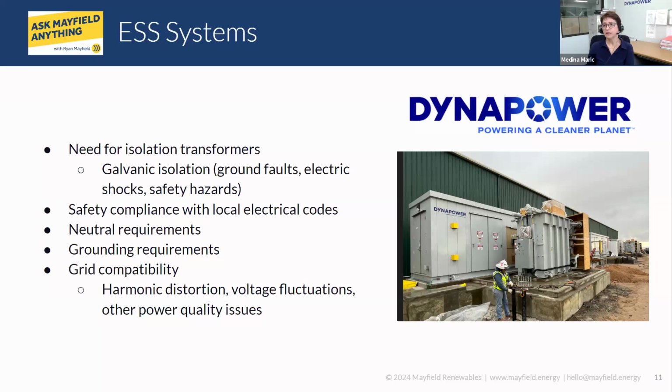That's usually a delta Y or delta YY connection. On the high voltage side, if we add an offset to the primary windings, like 7.5 degrees with two transformers working in combination to provide 24 pulse systems,